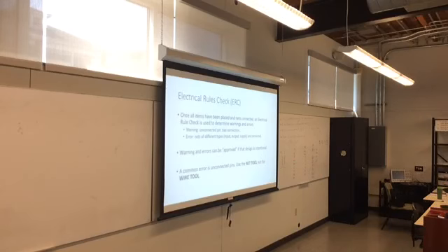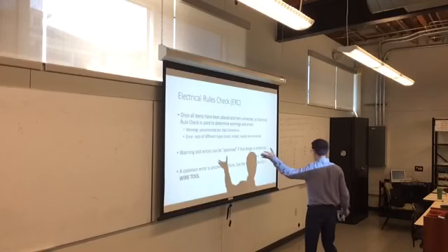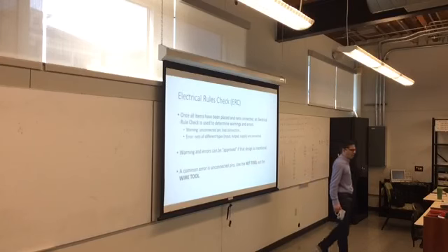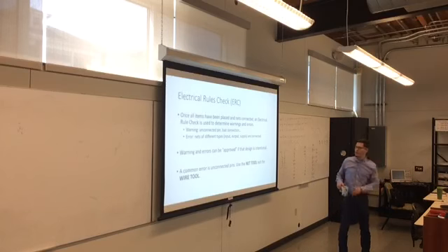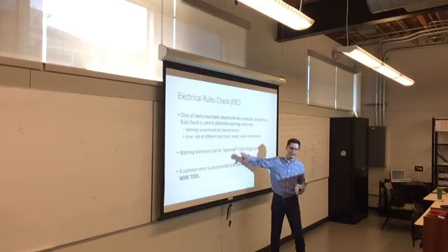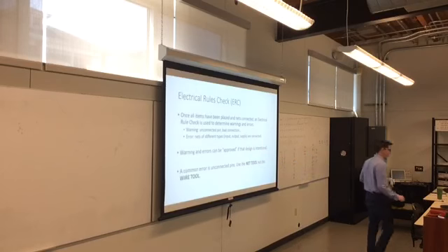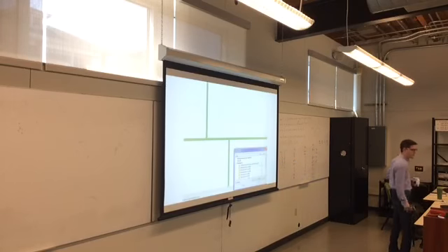Sometimes you want to do that. A lot of times it's going to give you an error saying, oh, the output of your power supply is connected to the output of your processor, that's VCC. And yes, that's fine, because the output of my power supply should go to the VCC line on my processor. If you get an error, it's like having a warning in a compiler. You probably should fix it, but if you know what you're doing, it'll be okay. So you can get electrical rule checks, but you can approve them, and you can wash them away.